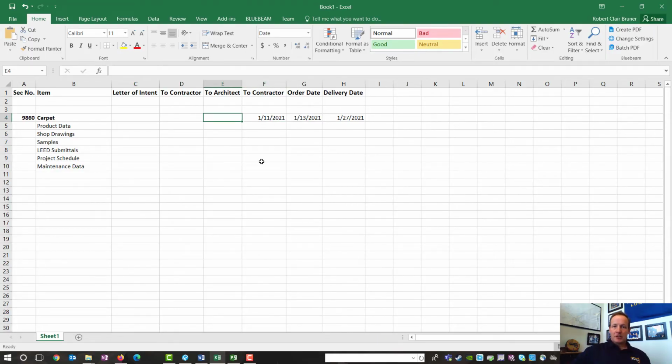From to the architect to contractor, that is the review time for the architect. Now, a minimum review time for an architect is usually 2 weeks. So let's give him or her at least 3. We want to make sure that we have time in there in case the architect rejects it and we need to resubmit it. So let's give 3 weeks. So that is this date minus 21 days. Okay.